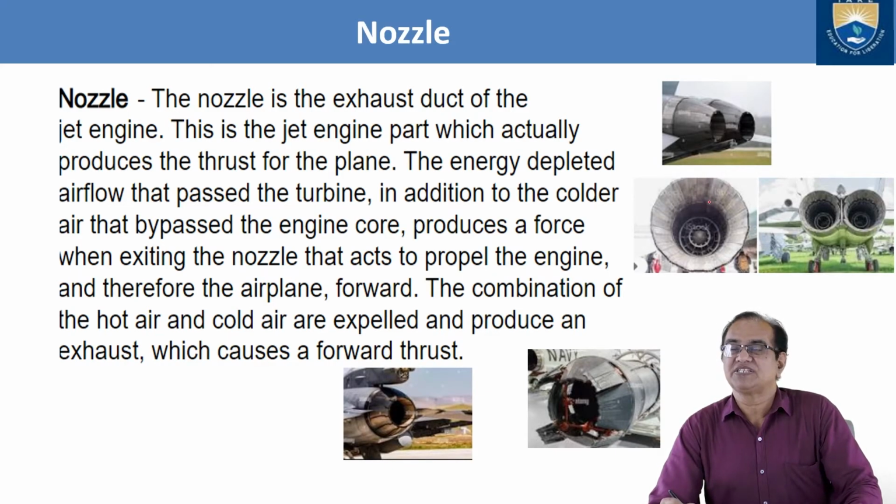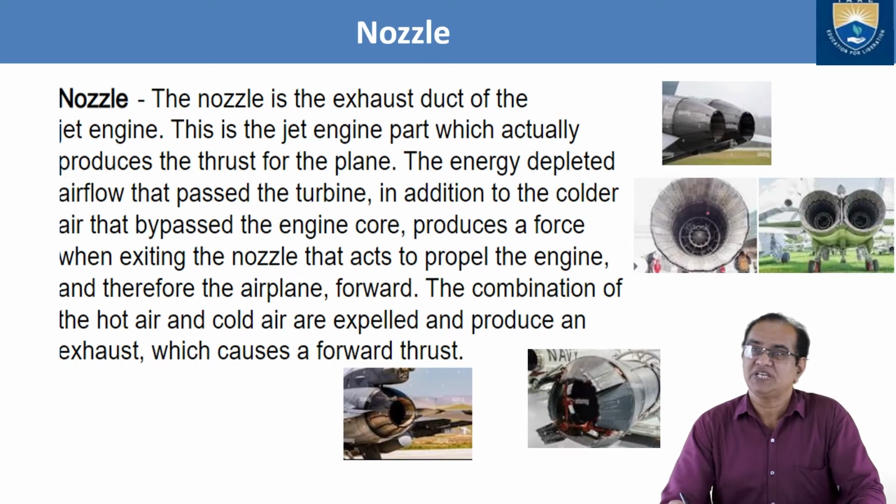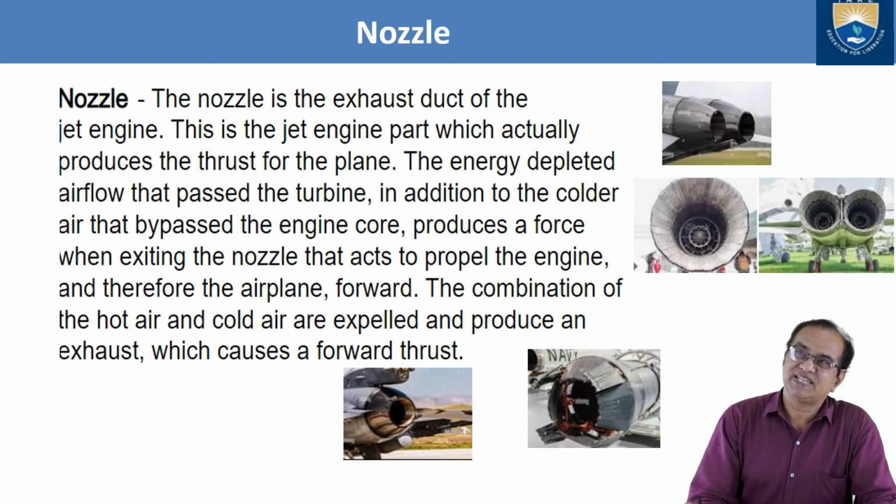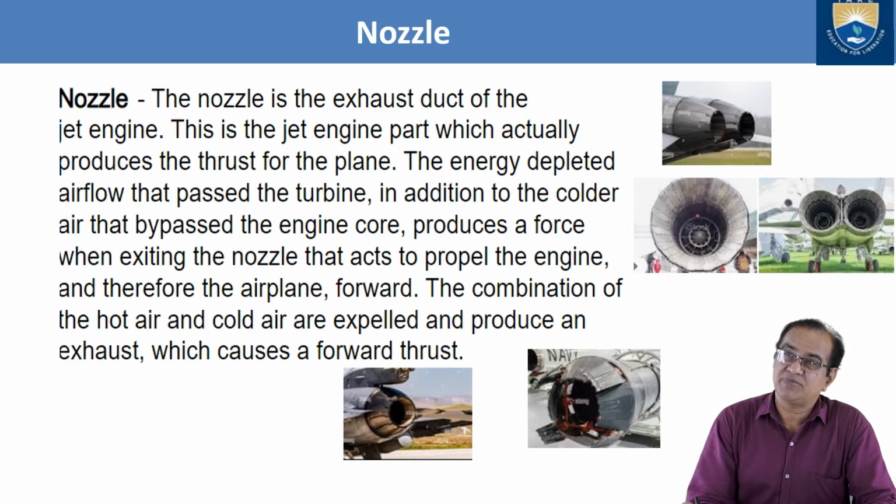The turbine is rotating and this will give a high amount of velocity for this pressure, and temperature will convert to the high velocity, and this high velocity will enter the nozzle. Inside the nozzle your gases will expand, and there is a mixture here. These mixtures mix the bypassed cool air and the hot air from the core of the engine. Both are mixed, and with a high velocity these are entering the nozzles. You can see different nozzles I have shown.